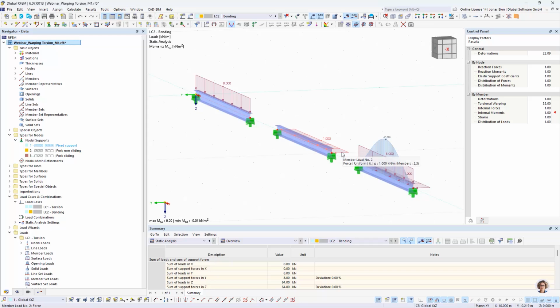And I don't want to make you nervous and say that always in the case where you have double bending, it has a critical influence on the design. I just want to raise the awareness that if you have a double bending or biaxial bending, there's probably, at least if you are working with non-warping free sections, some indirect torsion that is generated by this loading condition.